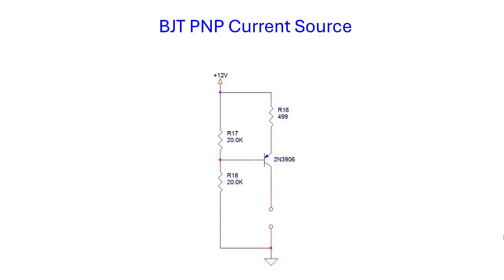Bipolar junction transistors can be configured for a constant current sink and a constant current source independent of the load resistance. Since there is a fixed voltage relationship between the base and the emitter of 0.65 volts, you can set up the base voltage and thus the emitter voltage to a certain value. Then the resistor value in the emitter completely determines the current through the collector.